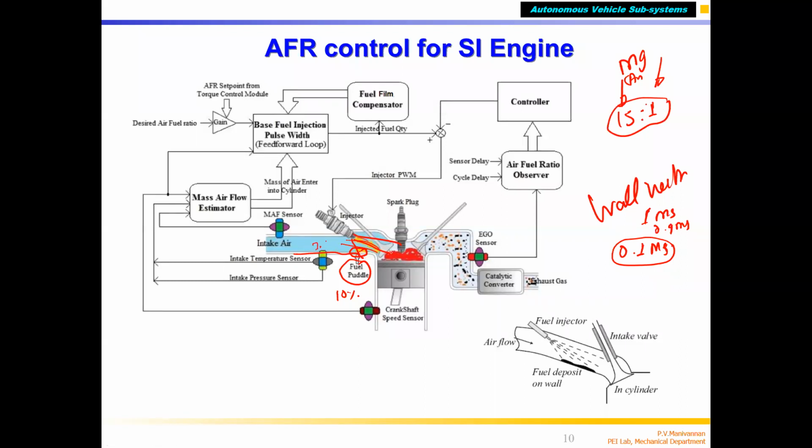Air went inside with 90% of the fuel. 10% of the fuel is sticking here. That fuel is also evaporating and going. By the end of the suction stroke, when the valve opens, maybe 0.05 milligram of fuel is not evaporated. Still, it is in liquid form. So that means what will happen? The amount of fuel that went inside your cylinder will be lesser by this much quantity, 0.05.